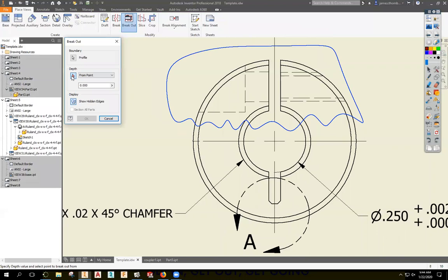I want to cut it halfway through a hole, right? What can I see here that's halfway through the hole? Which hidden line? Does this line count? Is that line halfway through the hole? No, because that's either the front side or the back side, right? If I pick here, it's going to go to the quadrant of the hole, either front side or back side.